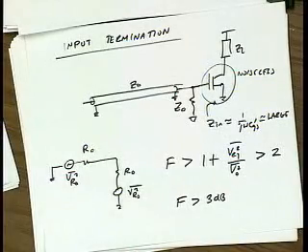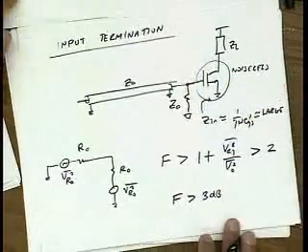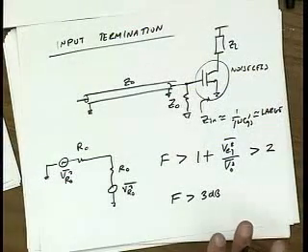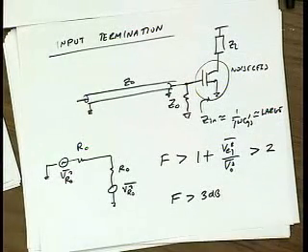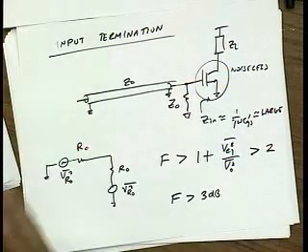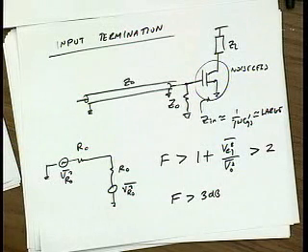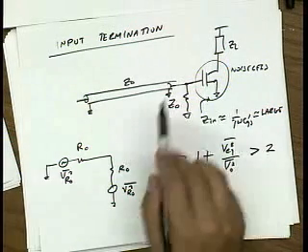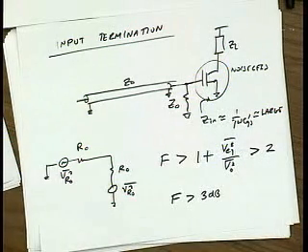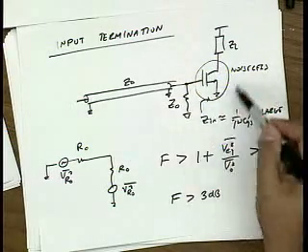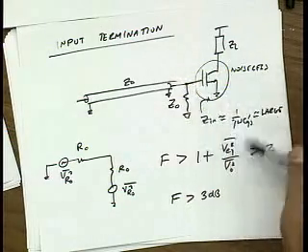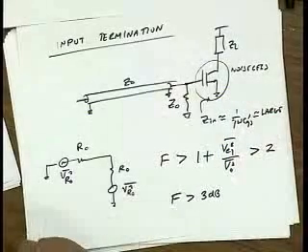Okay. Now, 3 dB noise figure is not terrible. It's not great. If you have a good amplifier, you can get down to really low noise figures of, let's say, 1.1, 1.2 dB. So you might say, it's not the best thing in the world, but it's still pretty good. 3 dB, hey, I'd be happy if I got a noise of 3 dB. But we neglected the noise of this transistor, right? That's also going to add. So now maybe it's 4 dB.